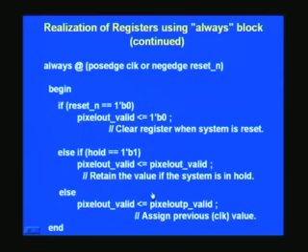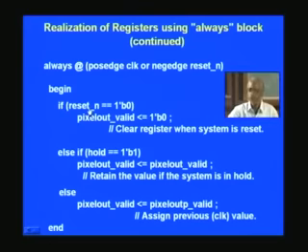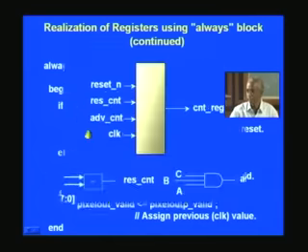Before we wind up with this example, we will see what it implies. An if statement puts a mux in hardware, and all of them put muxes. That means one mux output cascades with another mux and so on. That is the reason why I said you should restrict this to say 4 or 5, based upon our experience, as that would ultimately decide what frequency of operation you get, and that is an important thing to keep in mind as a designer. We will go on to the next example.